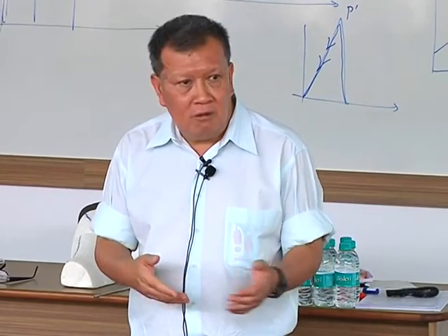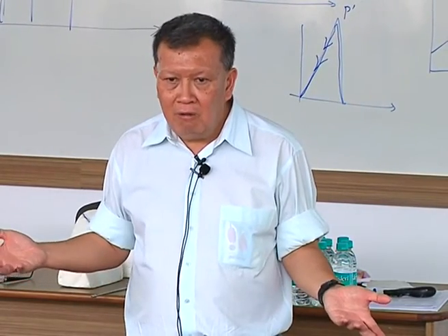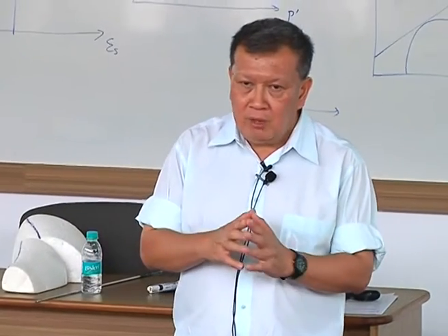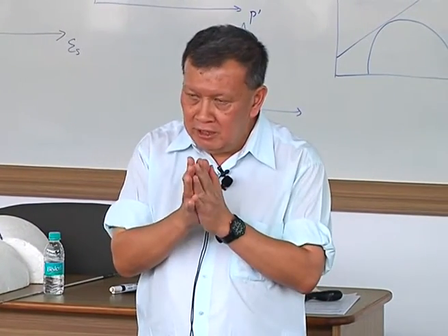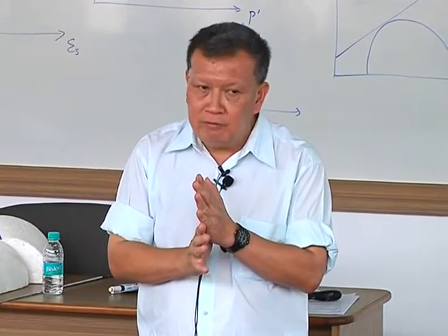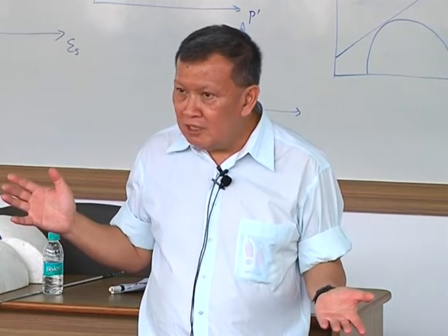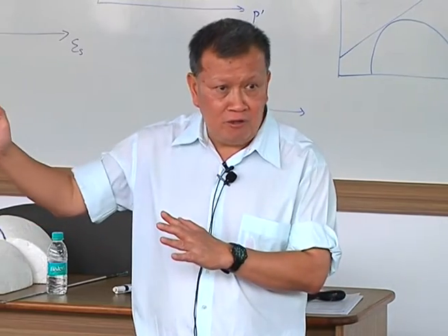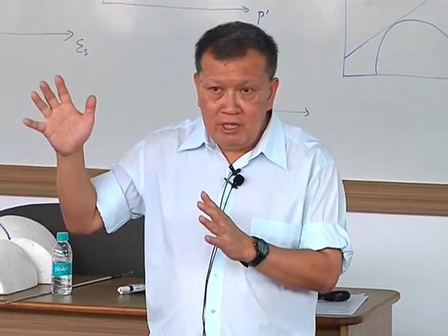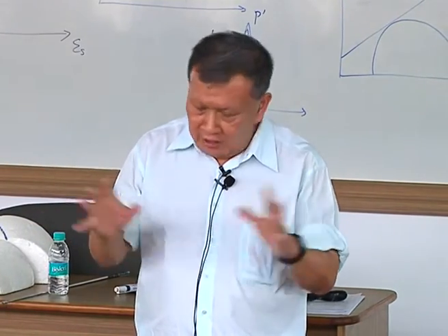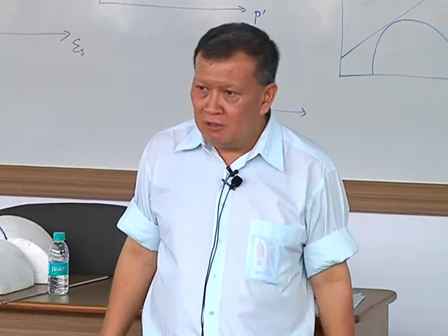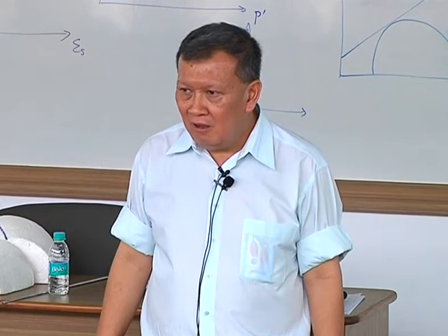The A parameter is 0. I said, why can't I use Mohr-Coulomb? And I used Mohr-Coulomb, and I did a series of parametric studies, came up with a representative E50, and the answer is almost spot on. I didn't know the answer when I was modeling it because it was before construction. About a year and a half after I modeled it, we saw the answer, and I was surprised by how good it was. Okay.